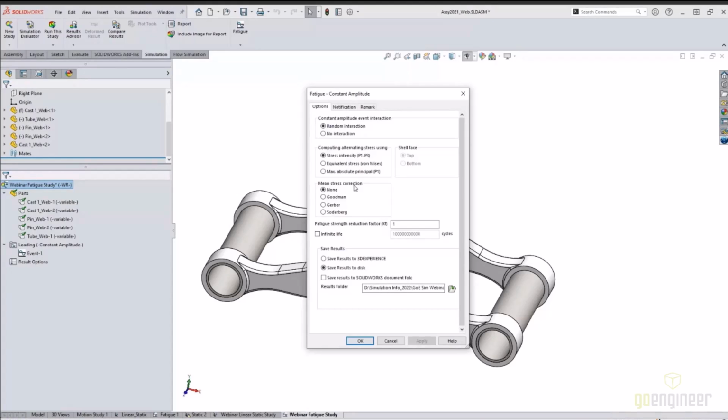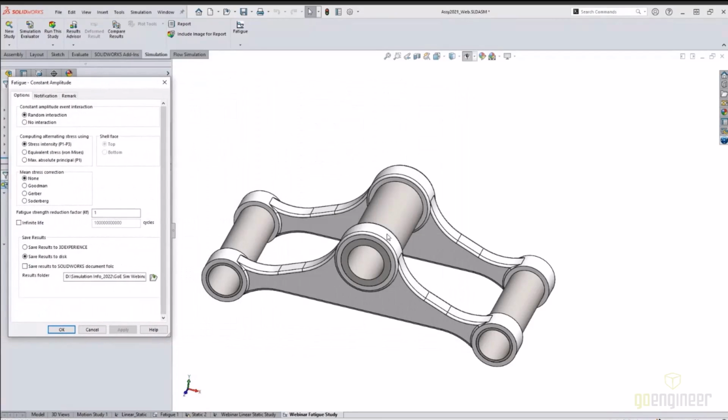Well, that's one style of loading. Maybe your style of loading is not that way. In this case, for this trunnion, it's completely fully reversed. What if you're pulling up here and pulling down? So we have two different methods of running a fatigue study: one lab test based, versus what you're doing in reality here.